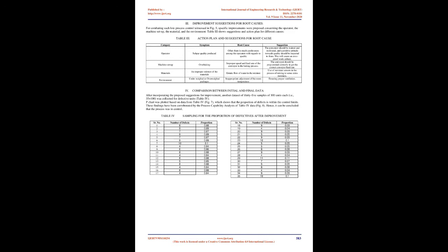According to the nature of data collected, there are two main categories of control charts, i.e., variable control chart and attribute control chart. A variable control chart is plotted to control process parameters, the data of which is continuous in nature. On the other hand, an attribute control chart is used to plot out data that tends to classify or count observations. A typical example of quality characteristic classification would be classifying units as defective and non-defective. Attribute control charts are further organized into P charts, NP charts, U charts, and C charts.